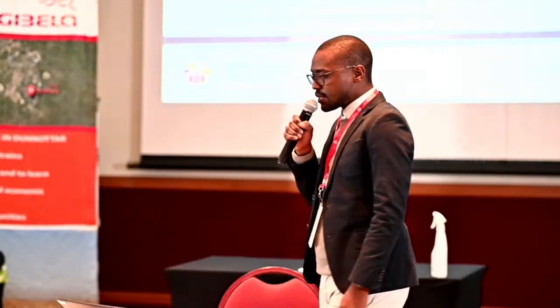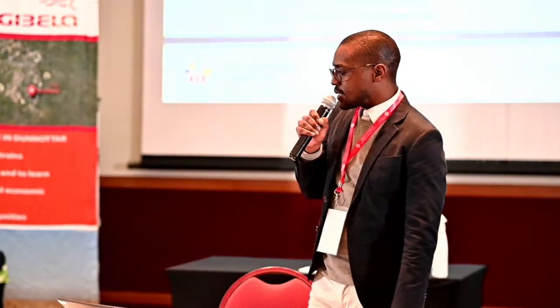So the research methodology. This shows in more depth the calculations that we used in terms of SAIDI and SAIFI to measure the actual interruptions. Just briefly, SAIDI is the System Average Interruption Duration Index. It basically measures the interruption from the time of the fault to when it was restored.